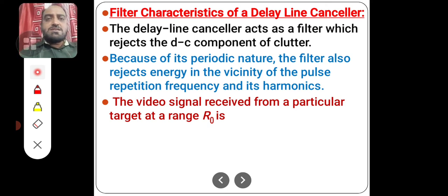So the received signal was first converted to a sound signal, which was passed through the water filled tubes. These tubes produce a delay. At the other end of the tube, a mic converts the sound signal back into an electrical signal, which was then given to a subtractor. That was the first case.